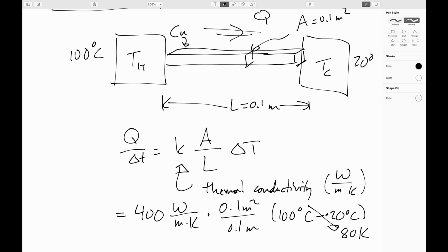You could have just left this as degrees C, but if you're not sure, it's never a mistake to convert those to Kelvin, and then you know for sure that you'll be okay. But generally speaking, if you have a temperature difference, there's no need to convert Celsius to Kelvin, because when you take the difference, a C degree is a Kelvin.